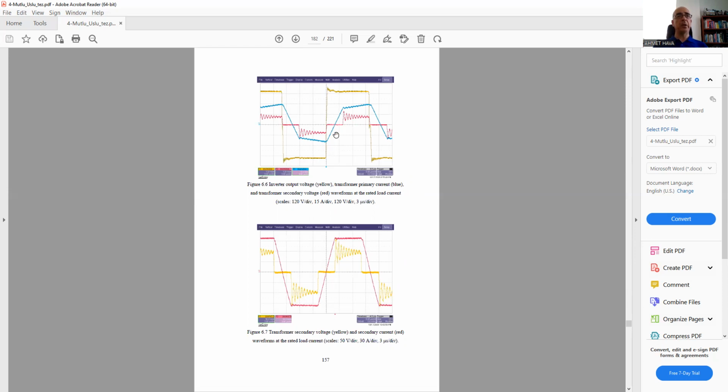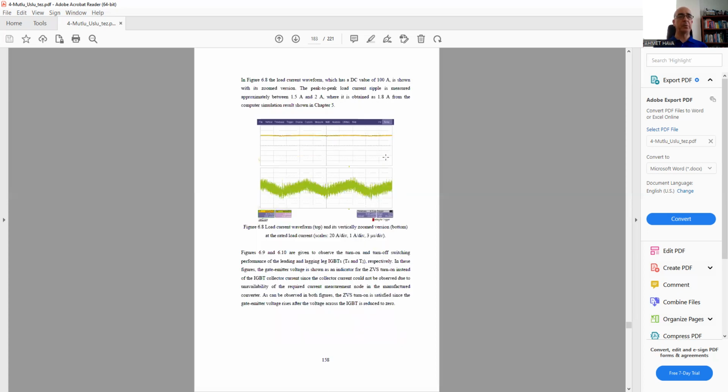Then you can illustrate and relate at t equals t0, what was the voltage, what was the current, what was the other component at the same specific time. So it is important, when it's necessary, to include as many waveforms in the same oscillogram as possible.